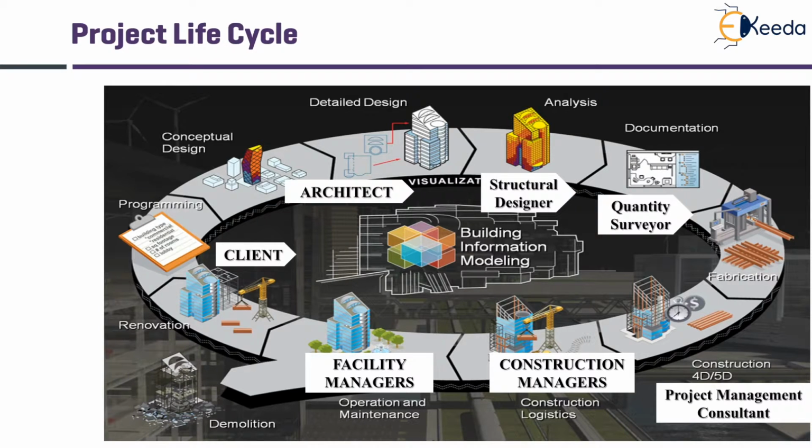Thus, the structural model is obtained. Next, we have documentation, wherein the quantity surveyor will extract different types of plans, quantity takeoffs, door window schedules, etc. These drawings can then be sent to the factory for fabrication. The factory will use these drawings to properly cut and prepare the pre-engineered building.